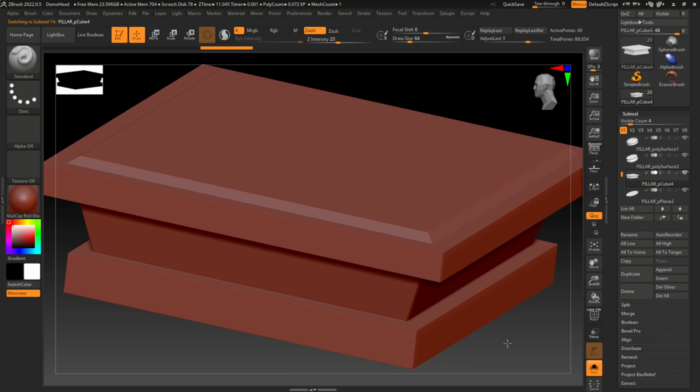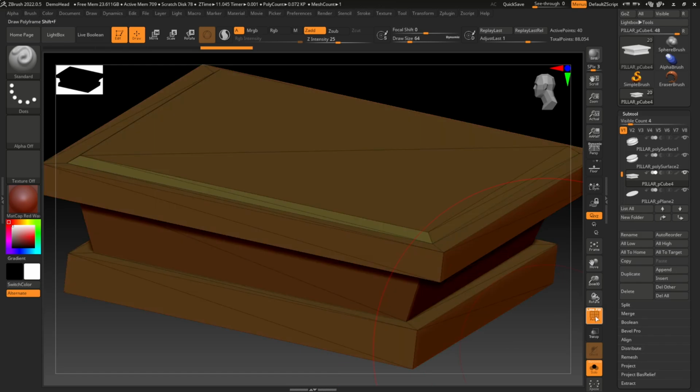For any modification or sculpting purpose, subdivision is required. Without subdivision, you cannot do anything. If you want to use a deformer inside Maya, what you do is subdivide the thing. For sculpting also, subdivision is required. See the subdivision here. It is not ready for sculpting. The subdivision is very low, right? Because we have done a basic blocking inside Maya and we have just imported a particular file.